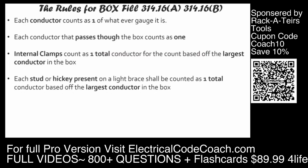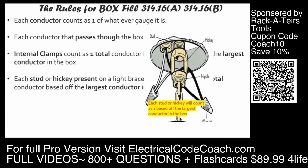Next, each stud or hickey that is present in the box shall count as 1 total based off the largest conductor that's in the box. Now, these are really old words, probably from the 30s if I had to imagine, but they still use them on examinations today. And this is what we're talking about. Imagine that we're hanging a chandelier. This we would call the stud or the nipple. But they're calling this the stud and this a hickey. And they still use this terminology on exams today, so you definitely need to understand.